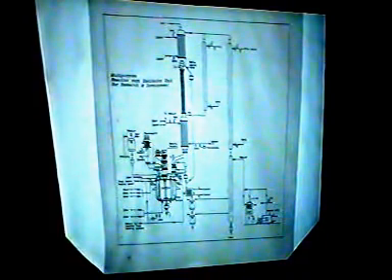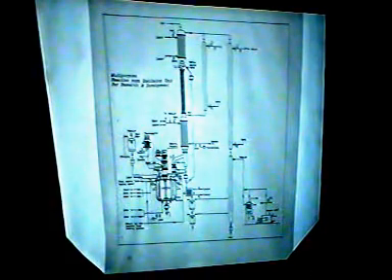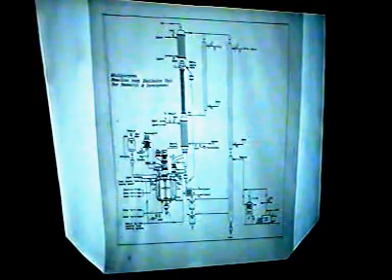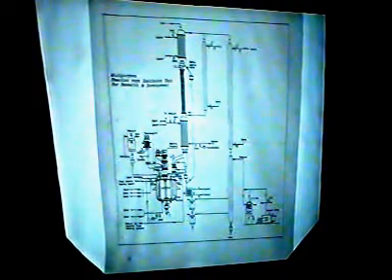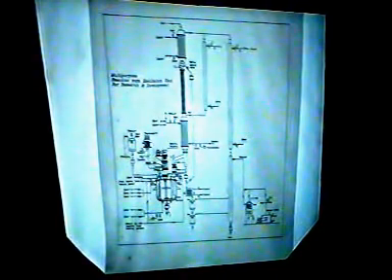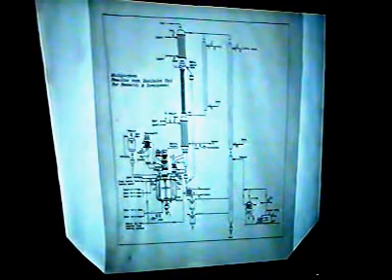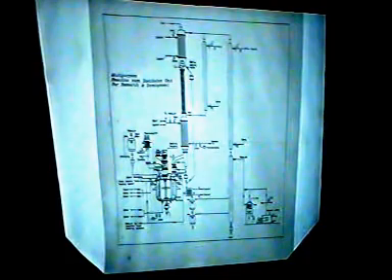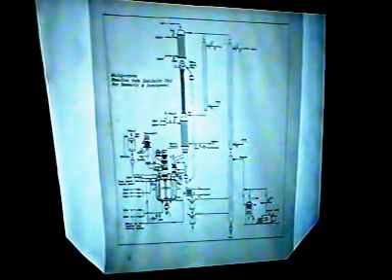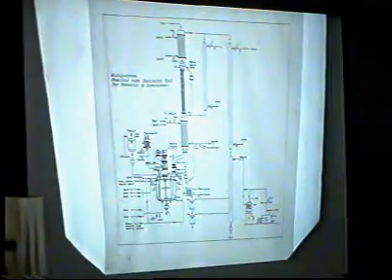The following additional attachments are provided to the vessel. There is a thermowell there, wherein we can insert a sensor for the thermometer, and a digital display thermometer is provided there. A pressure gauge, dial type, with an isolating valve, a safety relief valve in SS316, and a charging nozzle with an isolating valve.